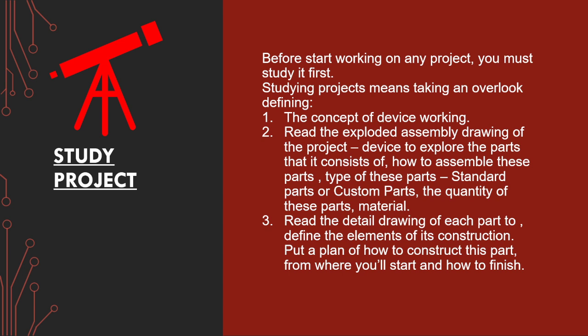We'll know what an exploded assembly is. It is a drawing used to explore the parts that the device consists of, how to assemble these parts, the type of these parts, standard or custom parts, quantity, material, etc. And at the end, we'll read the detailed drawing of each part to define the elements of its construction, and put a plan for how to construct this part, from where you will start and how to finish.